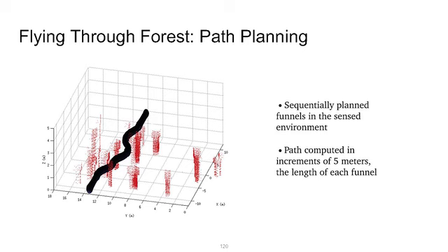So with the online planning algorithm, here's one of the possible paths. You have your point cloud of trees, yes, and those were shown previously, the little brown thing with the green foxy tree-looking things. Using a sensor model, you get the point cloud back, and as you're going, you plan your path. And the way that this works is every 5 meters you plan a path, and then as you're flying through it, you get new sensor information, and you can replan your path using the algorithm.